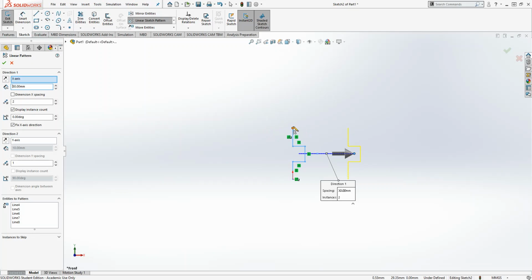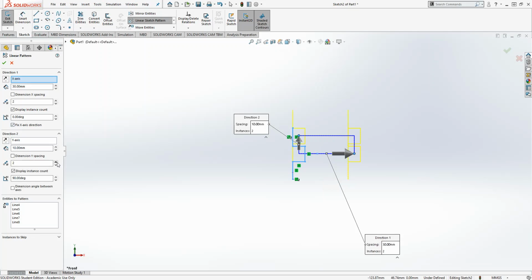So if I wanted to, right, I could take these parts right here, select them all, and I click linear sketch pattern, right? And as you can see, in the side menu and on the screen in the middle, this linear sketch pattern just takes these units or these certain items that you have in a sketch, whether it be lines, points, everything, and it transfers them, slides them over a linear distance, and repeats them. So you can see I have different kinds of things. I have direction 1, which is the X direction, right? That's currently what we see as a normal X direction, and the Y direction is upwards.